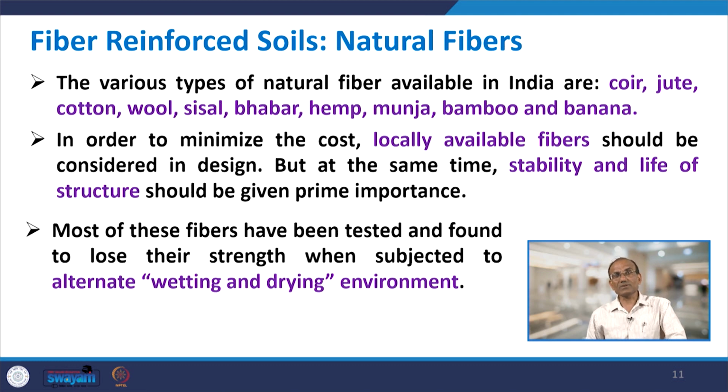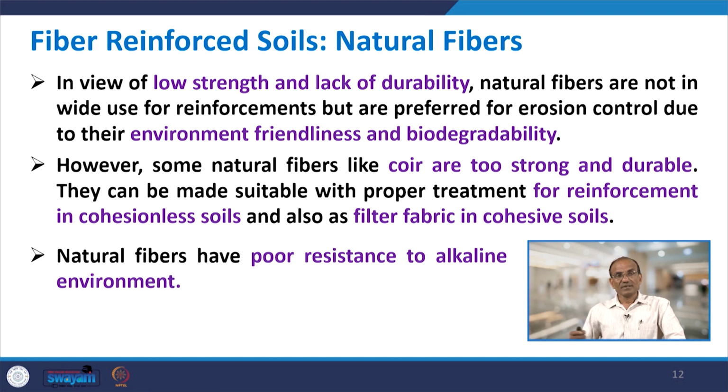In order to minimize the cost, locally available fiber should be considered in design, otherwise the transportation cost will increase, but at the same time the stability and life of the structure should be given prime importance. Many of these fibers have been tested and found to lose their strength when subjected to alternate wetting and drying environment. In view of the low strength and lack of durability, natural fibers are not widely used for reinforcement, but are preferred for, for example, erosion control or pavement design due to their environment friendliness and biodegradability.